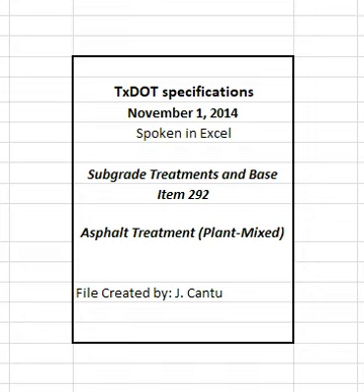If required, verify that emulsified asphalt proposed for use meets the minimum residual asphalt percentage specified in item 300, asphalts, oils, and emulsions. The engineer will obtain at least one sample of the TxDOT binder per project and test to verify compliance with item 300, asphalts, oils, and emulsions. The engineer will obtain the sample from the asphalt distributor immediately before use.